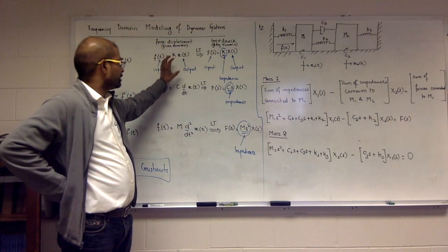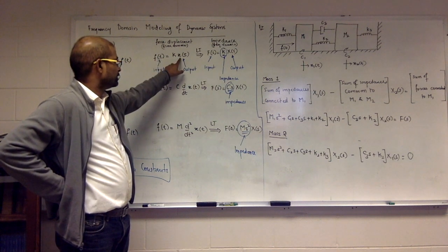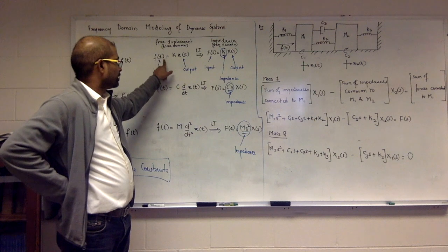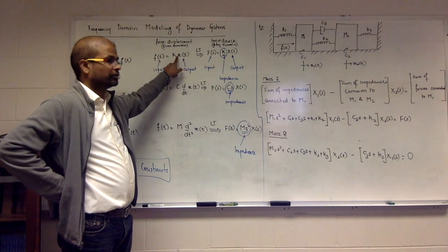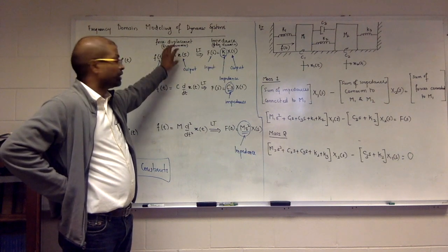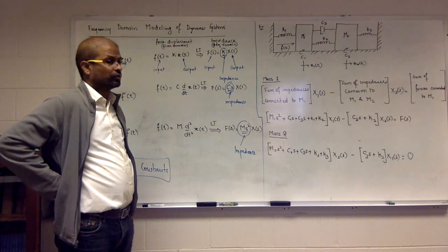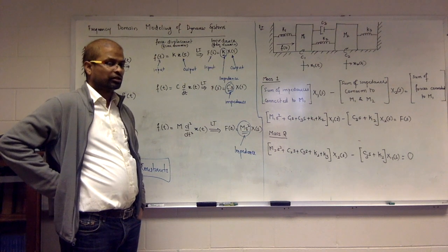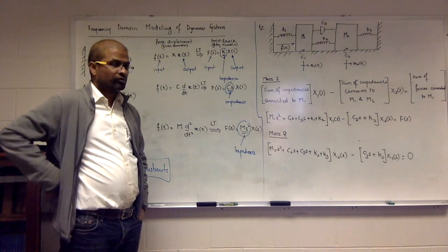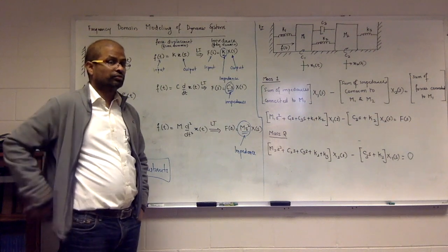So you can say that force is proportional to displacement for a spring. It depends on what kind of spring you use, what the material is, how many coils you have, how closely they are spaced, what the gauge of the coil is.